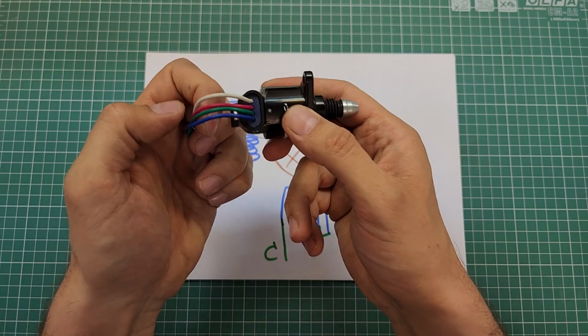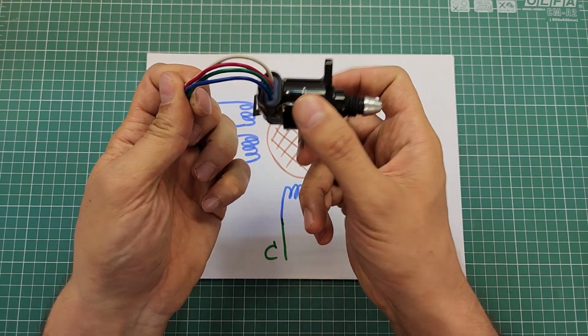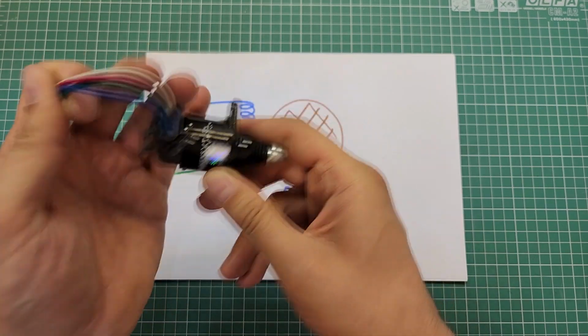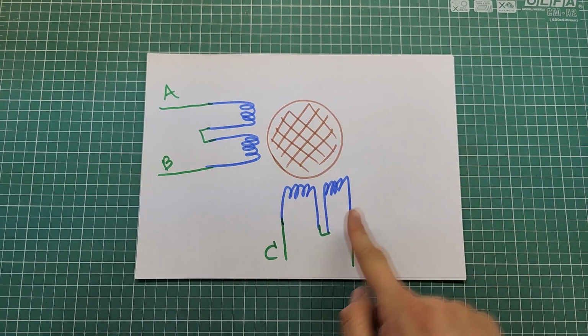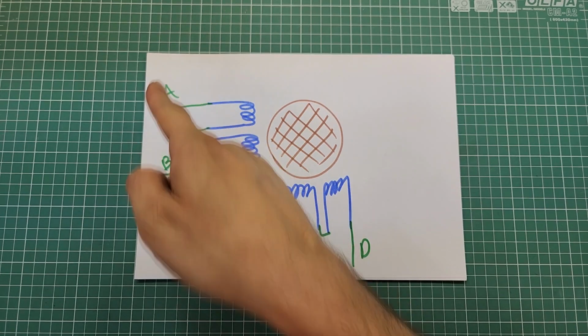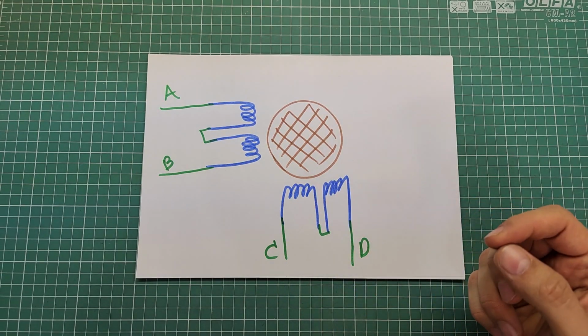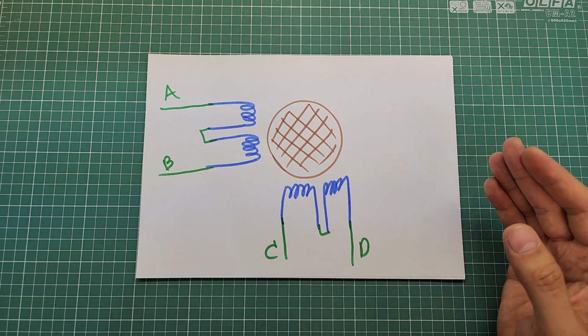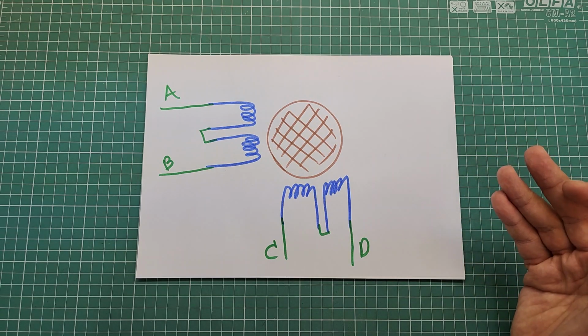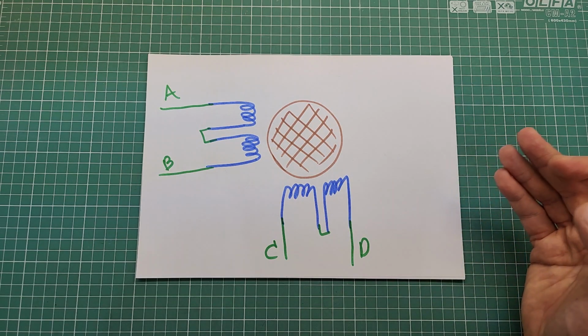And finally, if the motor has 4 wires like this car engine stepper motor, the inner wiring is something like this and only points A, B, C and D are pulled out. Remember, I'm talking about ordinary stepper motors. I mean, maybe there are other stepper motors with other structures. You have to be careful.